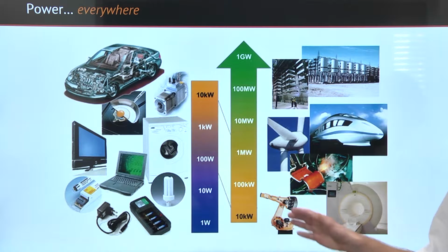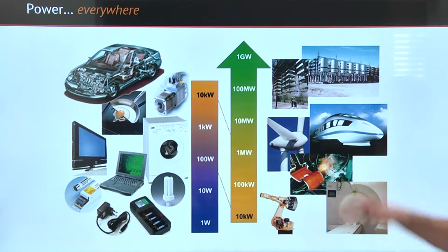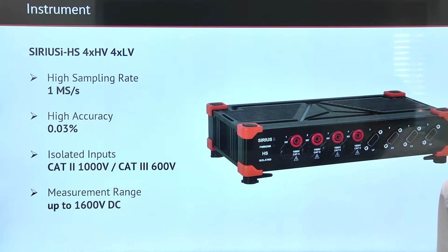Power will be measured from low power appliances up to really high power appliances like at wind power plants or in the transportation sector. And for these applications we need a power analyzer with certain requirements. On the one side we need high sampling rate, highest accuracy, isolated inputs, and also a certain measurement range to fulfill these requirements.